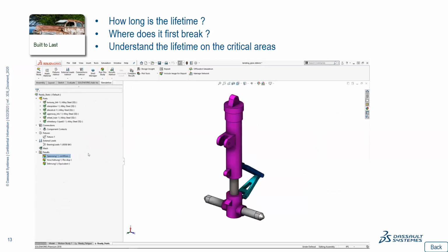So this type of area is very important if you want to estimate the life of your products and to anticipate, for example, some maintenance. You can say, for example, I design a product and I know that with this design, this product can resist only, let's say, 10,000 cycles of load. So maybe every 2 years, you will have to do a maintenance to anticipate the failure of this product.